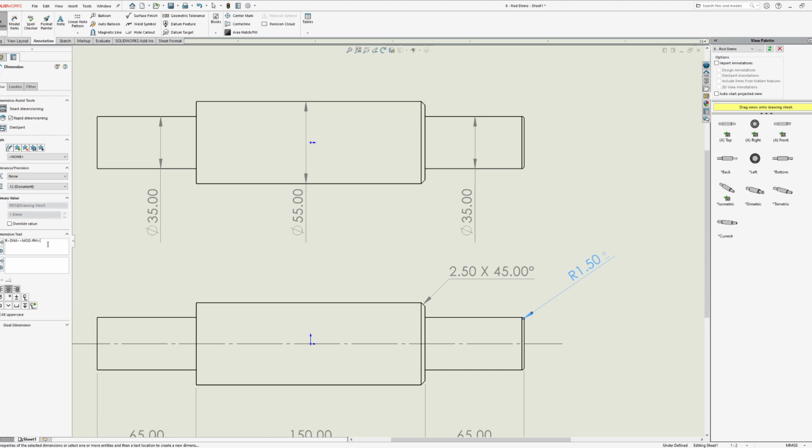Maybe I know that 1.5 millimeters is a pretty darn hard measurement to actually get. So I'll say, well, it could be 1.5 with a tenth of a millimeter tolerance there, or even more so, a quarter millimeter tolerance. So that's other information that might be relevant to your diagram. You also see some other symbols here, like our countersink or counterbore, as well as depth. So pretty much everything that SolidWorks can do in order to do a specific callout, you can add those aspects there as well.